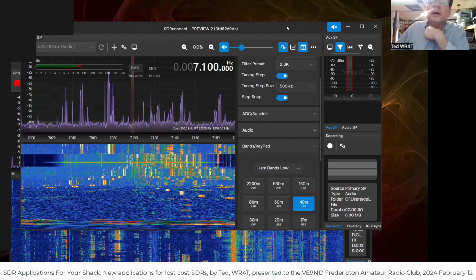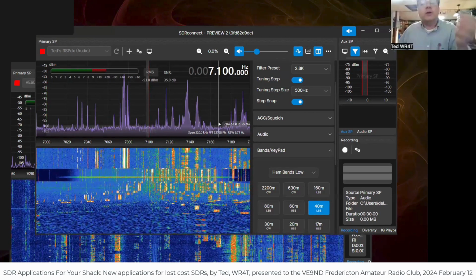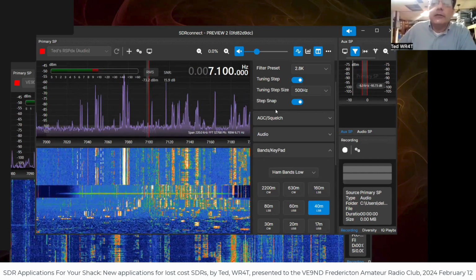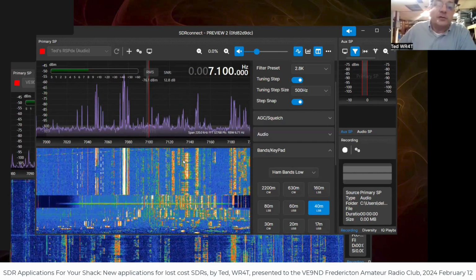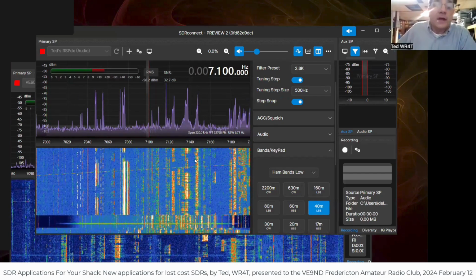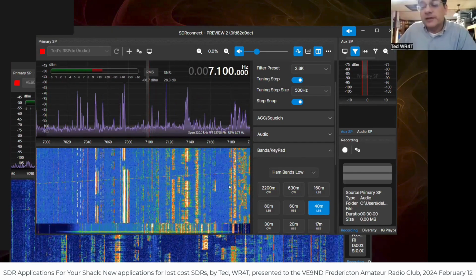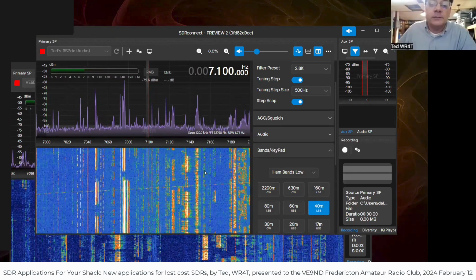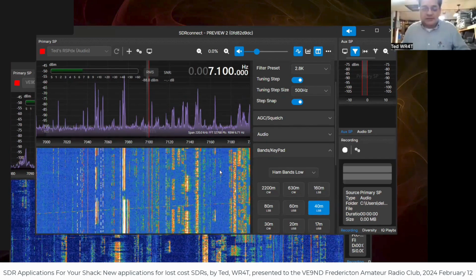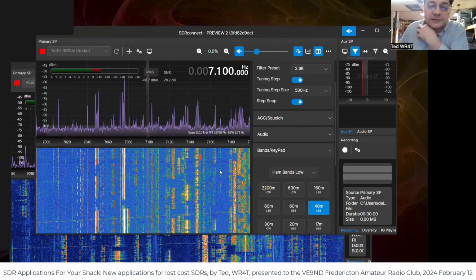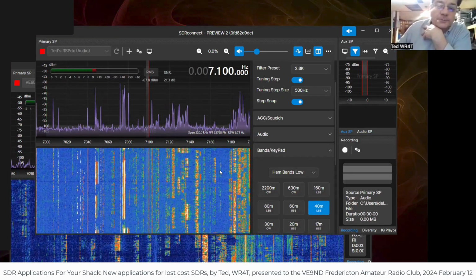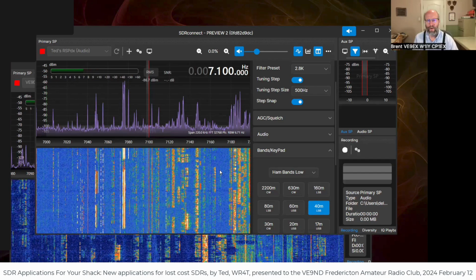Okay. So if I have the 40-meter band selected as the first one to connect, the next user that connects to the radio will automatically be tuned to the same band segment. They can listen to any of the signals in the band. They can tune to any one they want, but they'll be using the same band segment that the first user selects. So that's the only limitation when you have multiple users that connect. Yeah, if you want to try, Malcolm.